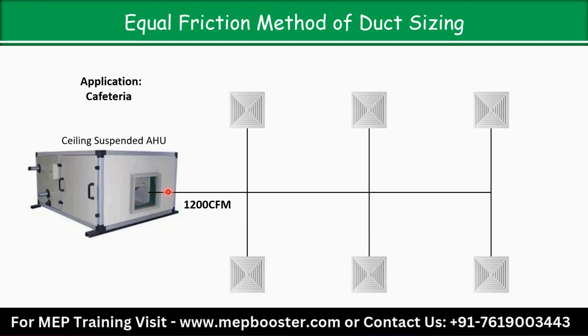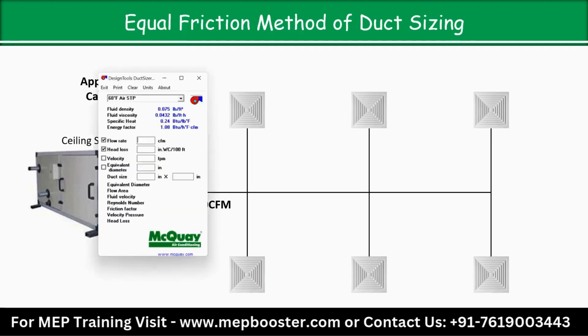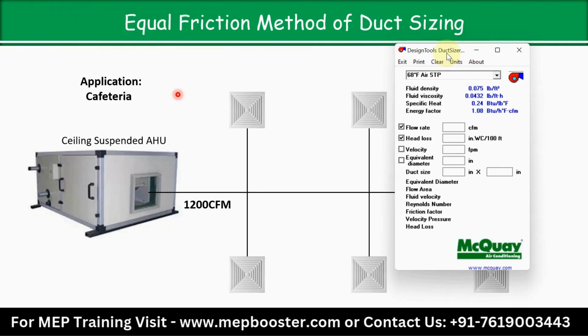So first of all, let's start how to do the duct sizing by using the equal friction method. Can you see here 1200? First you have to open the McQuay duct sizer software. You can see here I have opened the McQuay duct sizer software. In that software, if you are using the equal friction method, 2 parameters you have to enter: flow rate and head loss, means friction loss value. Automatically the system will give you the velocity and equivalent diameter. Here the flow rate is 1200, and the head loss which we have to maintain, as I already discussed with you,